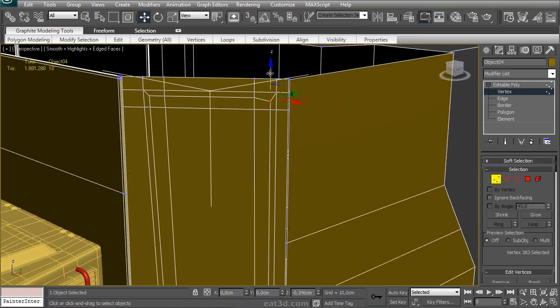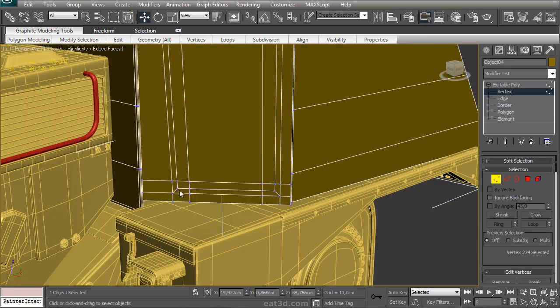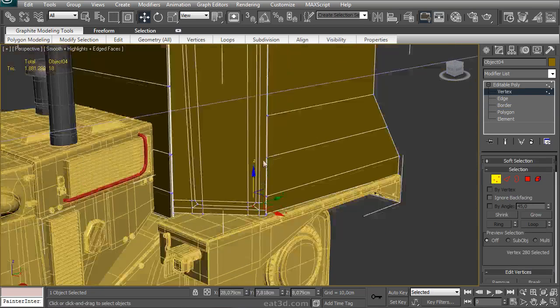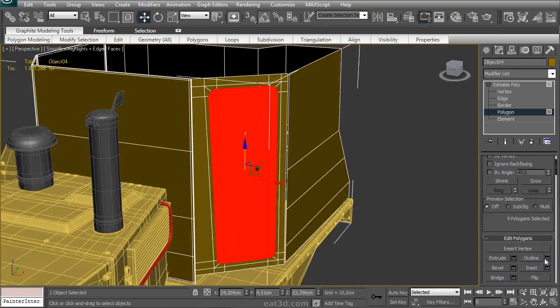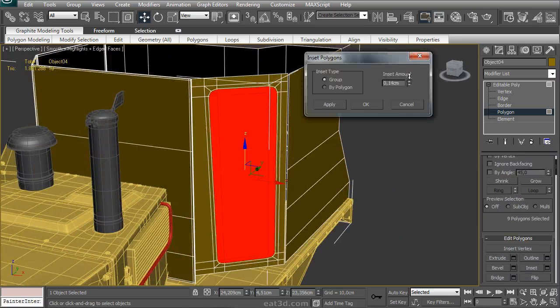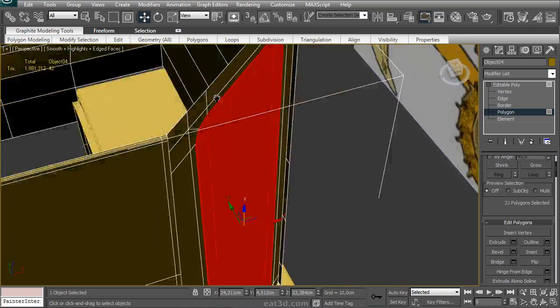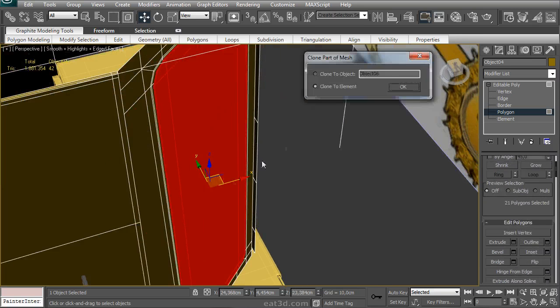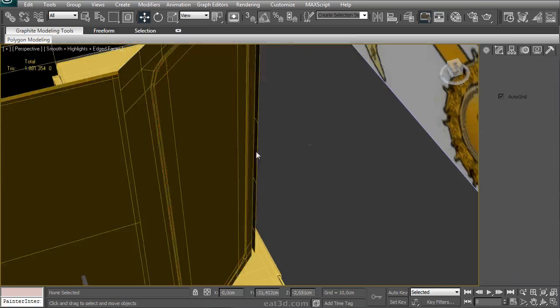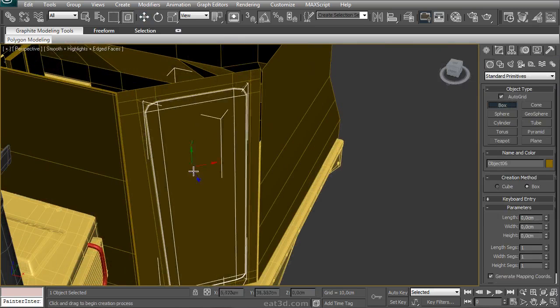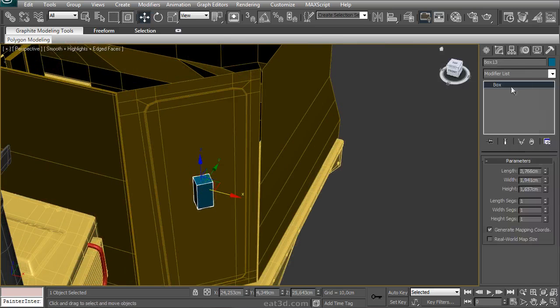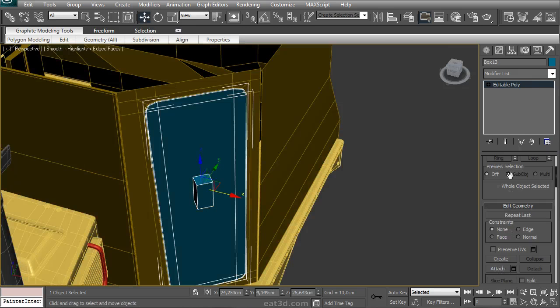You can see I performed an inset. Why? Well, the edges of this door are rounded, and I think if I use an inset, I can get that rounded shape to look better once the smoothing goes on. So look at that. That's my door shape. Forming an extra inset just to make sure that the edges are rounded nicely. And then I'm doing an extrude. And I've also detached that to a separate part. Why? Because the door is a separate part.